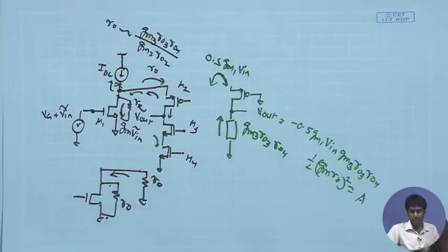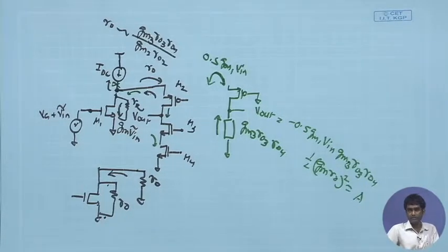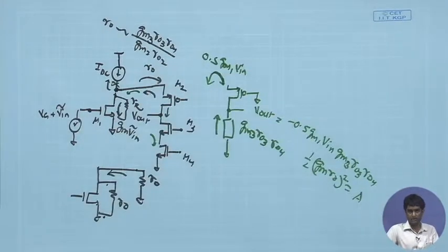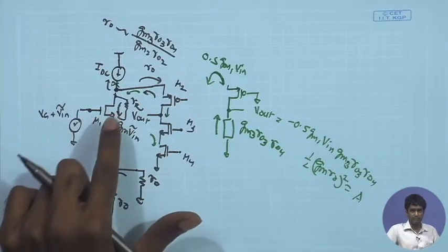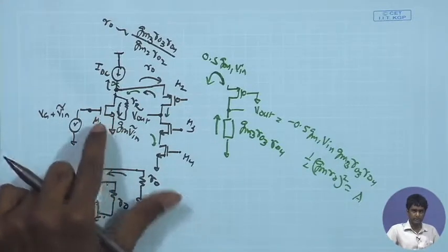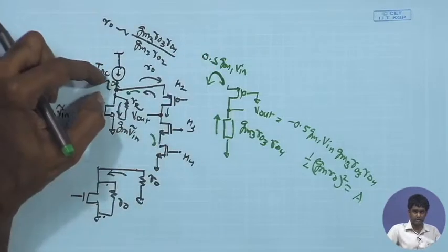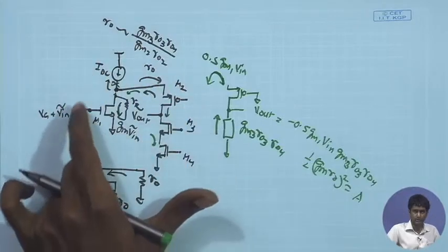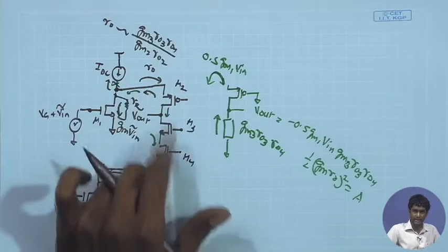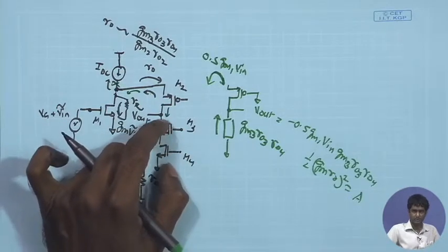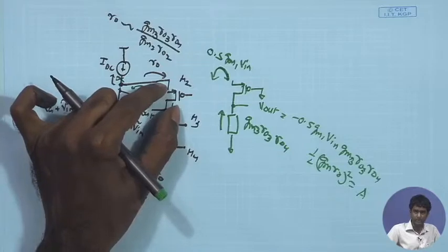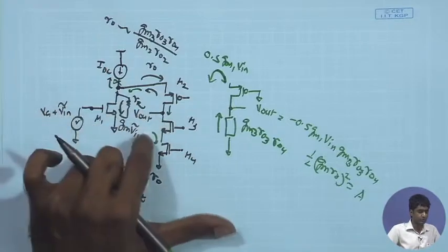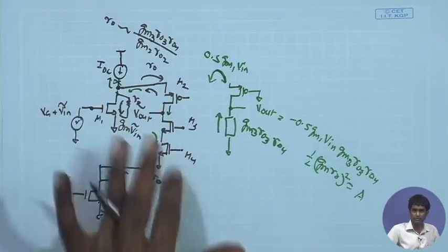This is your gain. So, this is again giving us the same functionality, same behavior as our normal stacked cascode amplifier that we saw. Only difference is that we have applied the input signal to the gate of the NMOS, and rather than sending the current into the stack of a cascode NMOS and a stacked PMOS load, we have folded the current. The small signal current has been folded down, and now it is going to the stack of the NMOS cascode load and a PMOS cascode device. This is a cascode transistor, this is a PMOS cascode device, and you are having a cascode load. So, the small signal current has been folded down, and therefore, we term this as a folded cascode.